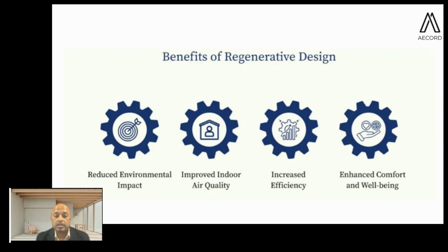So there are new stringent norms which have come into building air filtration systems, where we have to go for a high level of filtration to maintain a better indoor air quality. And in places like Delhi, we already know that at least in office buildings, we have the option of putting up high efficiency filters and technology. But what about the residential sector? You really can't put up high efficiency filters and carbon filters and other things in a residential unit in a tropical climate, because we don't have centralized air conditioning systems. So it is more hampering to the residential building sector, where we have very bad indoor air quality in the urban scenario, and somehow we are enhancing our technologies in the commercial and office scenario, but residential still has a drawback of poor indoor air quality.